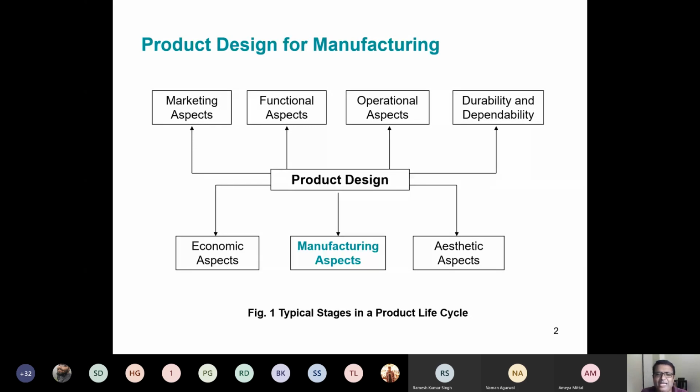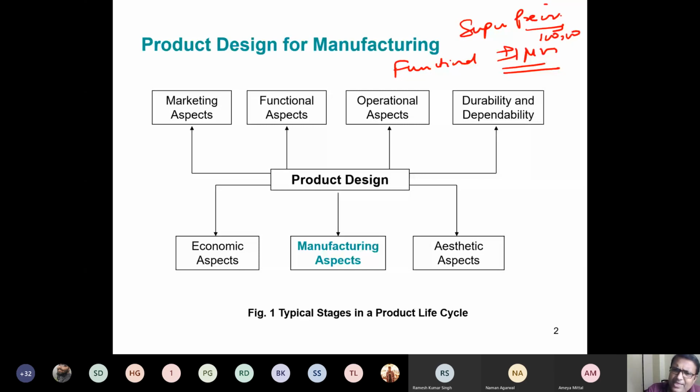Yes, application. What is the functional requirement, right? Why would I give a tolerance of plus minus 1 micron? Can you tell me a place where this might be important? Plus minus 1 micron? If it's a super precise bearing going at say 100,000 RPM, I need these tolerances. Aerospace maybe, but there are a lot of other applications, especially applications where you have high rotating speeds. Aerospace can be one of the applications, but aerospace are larger applications, so you cannot have such tight tolerances.